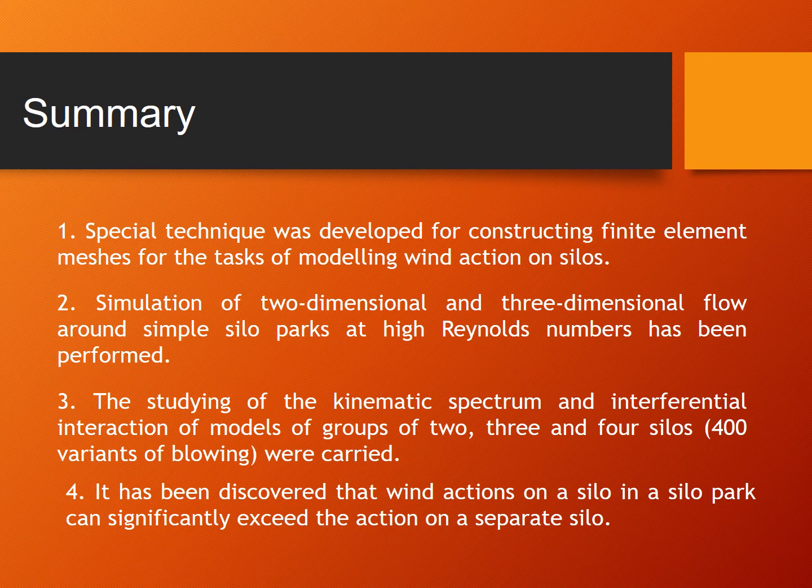Based on the carried-out verification test, a special technique was developed for constructing finite element meshes for the task of modeling wind action on silos. Simulation of two-dimensional and three-dimensional flow around simple silo parks at high Reynolds number has been performed.